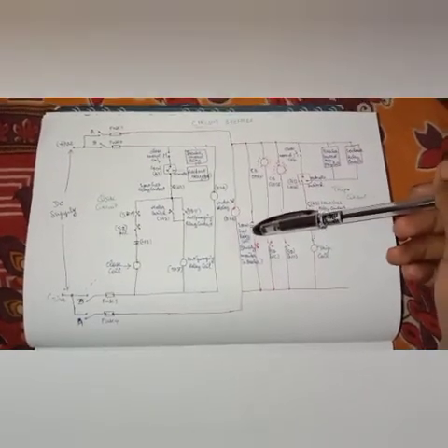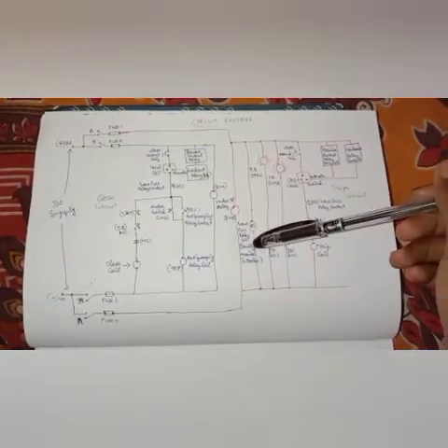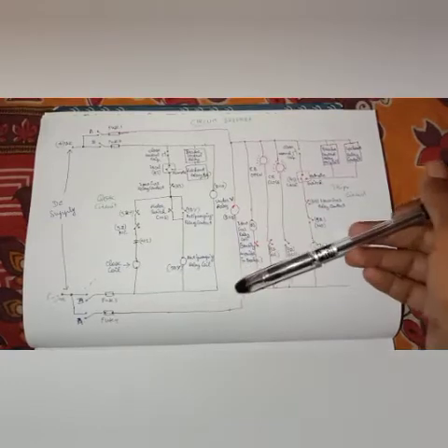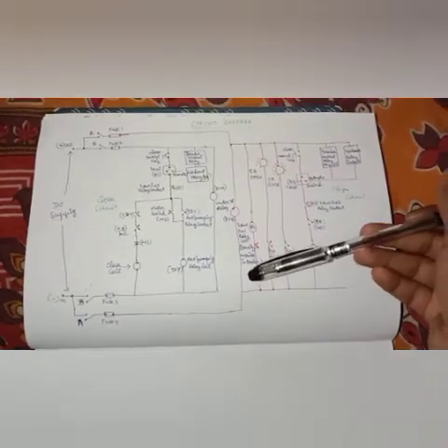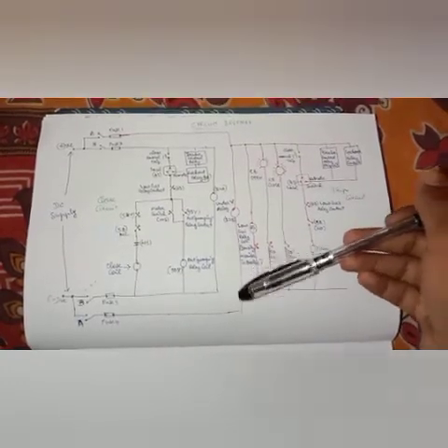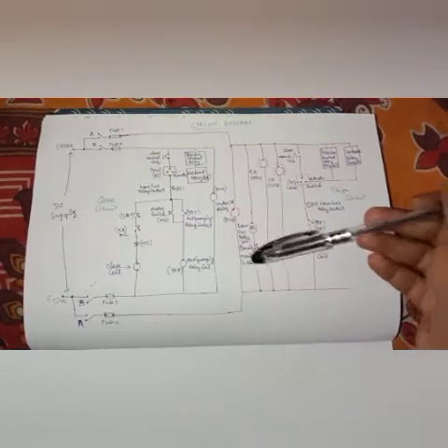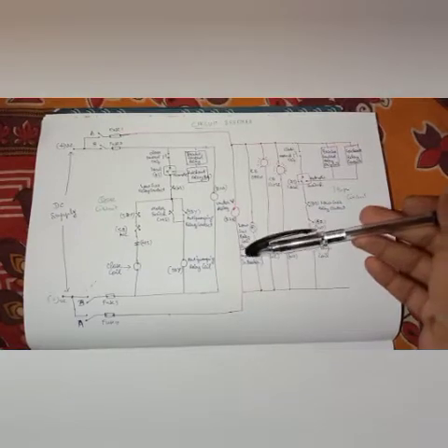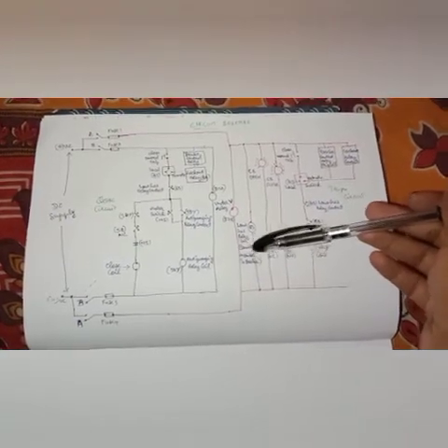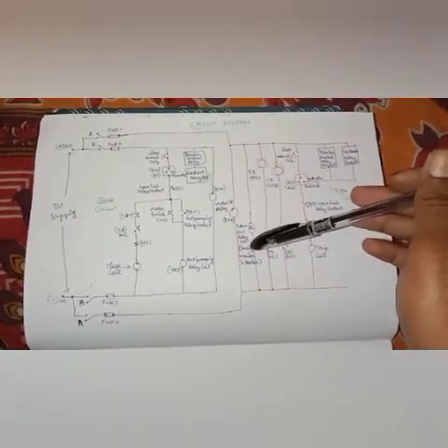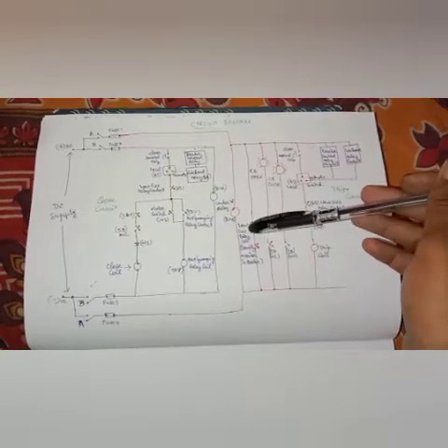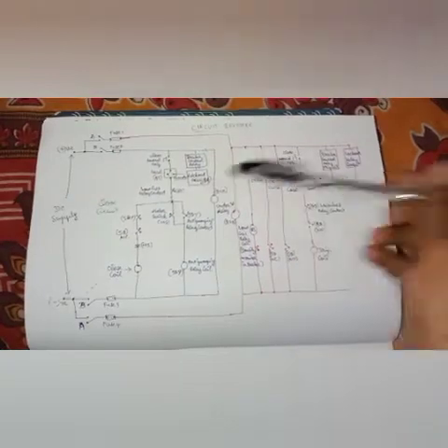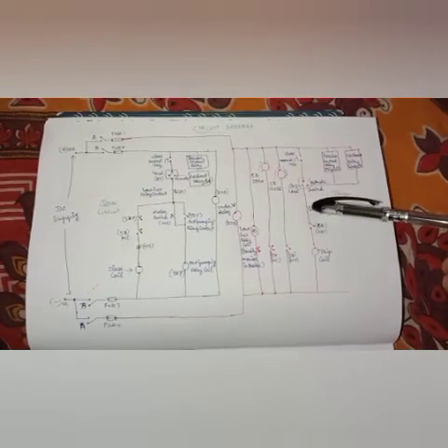This coil will get energized if there is any low level of gas or oil or anything, according to the breaker which we are using; we will take the gas relay or oil relay, likewise I'm saying. So once it gets initiated, this coil gets energized and it breaks the closing and tripping circuits.